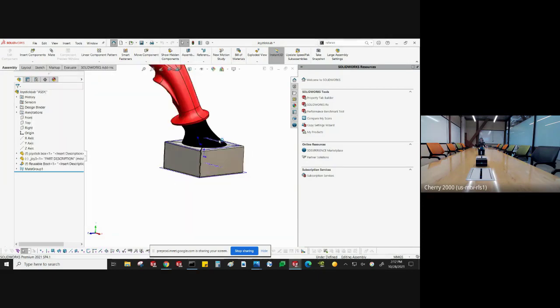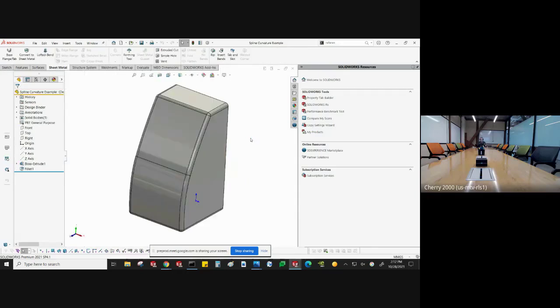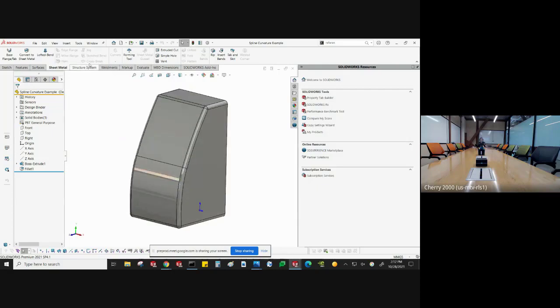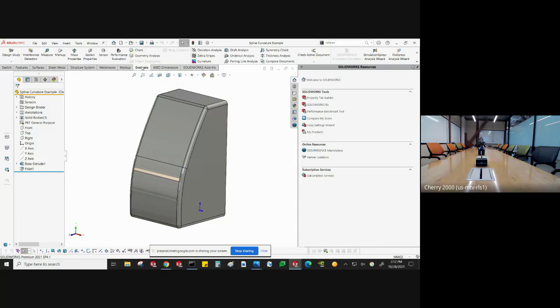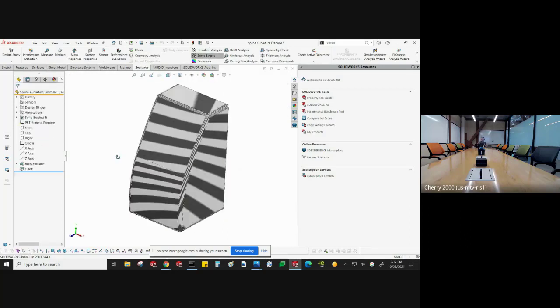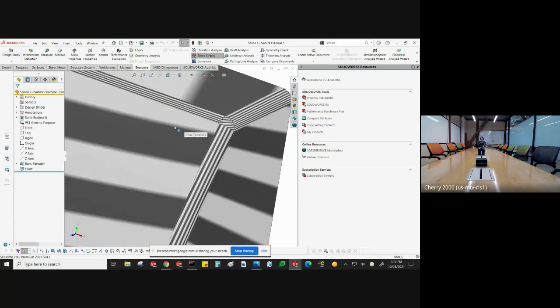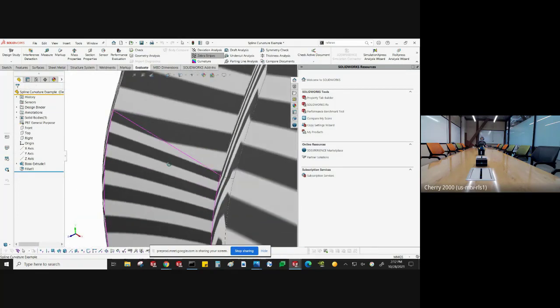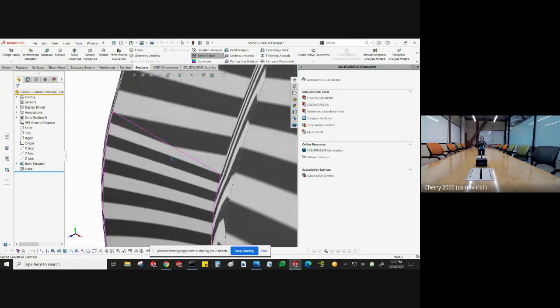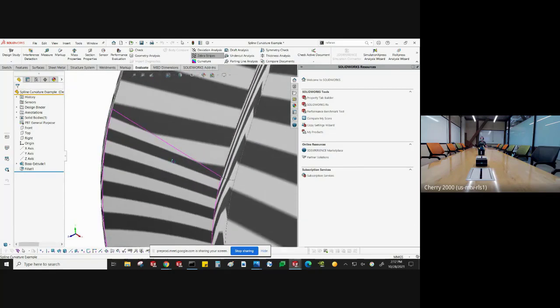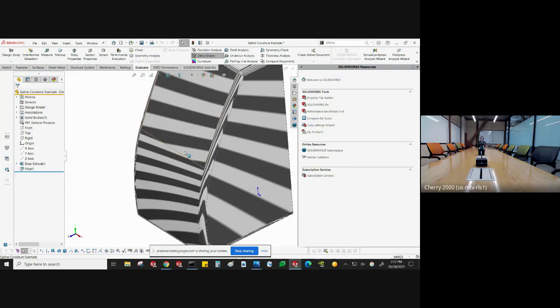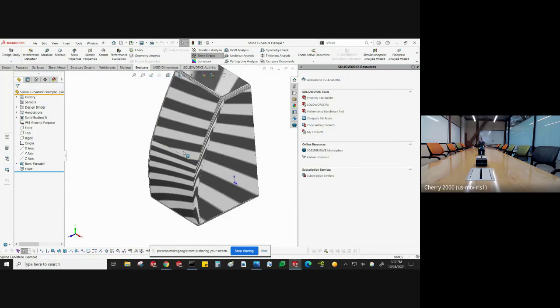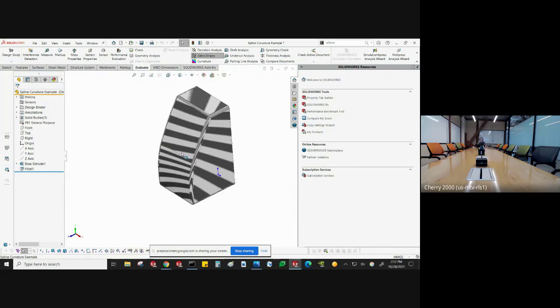Another thing that they've done is they've continued to improve the spline capabilities when you're making surfaces and things like that. I get on my evaluate, I can put on these zebra stripes, and this will show me whether or not edges have curvature or tangency or things like that. And you can see that when you see something like this happening, it's not a completely smooth curve. There's going to be a little bit of an edge there. So it's something called C3 curvature.